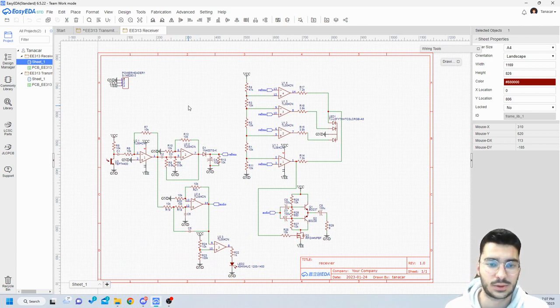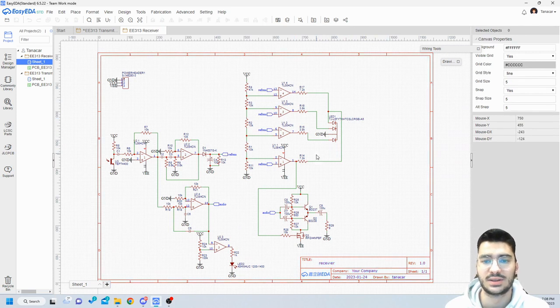And then there's a half bridge rectifier to detect the peak amplitude of our reference signal. Then this reference signal is passed through this comparator network. There are 4 different levels of signal intensity. Depending on the signal levels, the RGB here has different states, and we create states such that it would generate green for the most powerful signals, and red for the least powerful signals, and intermediate color values with distinct transitions for the middle states.